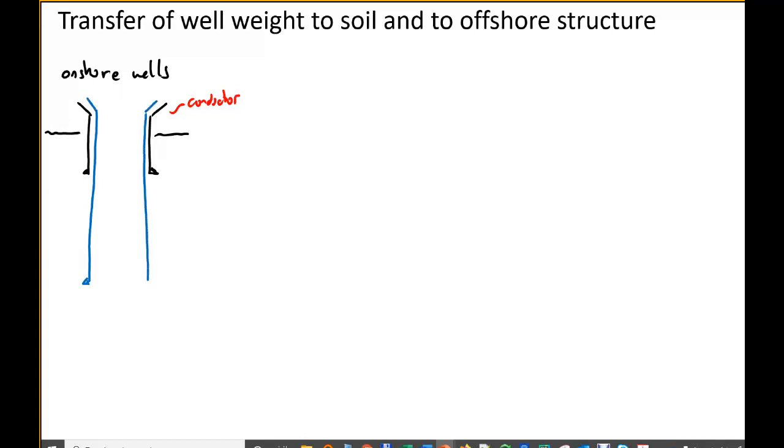Okay, so you have something called the casing hanger, the bowl of the conductor, where you hang the new one, the surface casing. Okay, then you have one more which is going to be hung on the previous, and so forth, and you continue like that for all, even for the tubing.